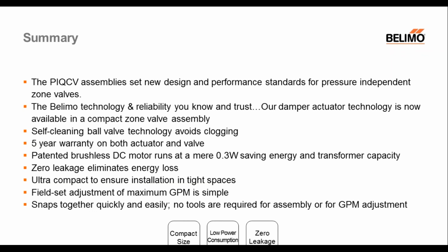The valves are zero leakage, and this eliminates lost energy. With some of the linear valves, as the seats wear or the stem has buildup or the seat has a buildup, you might be in your closed position, but you're not really closing off, so you can have some leakage.